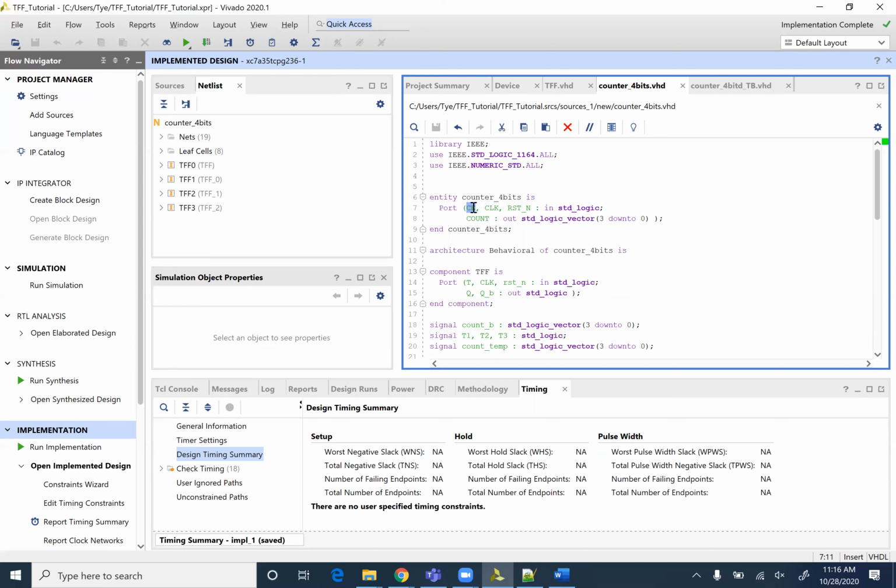One is it could just be hardwired to an internal oscillator that is making the clock, and it's outputting it there to make it easy for you to access. The other way is some of the FPGAs, many in fact, will require an external oscillator in order to have a clock. So it would actually be an input pin provided to the FPGA.